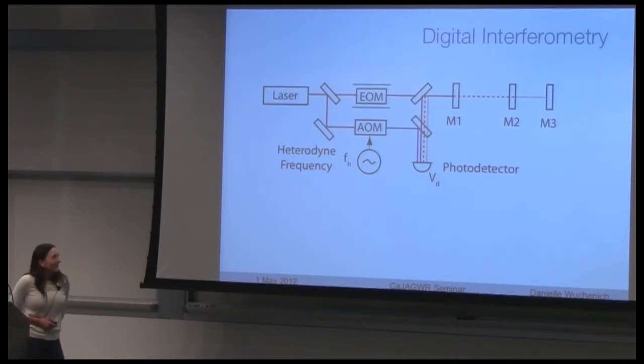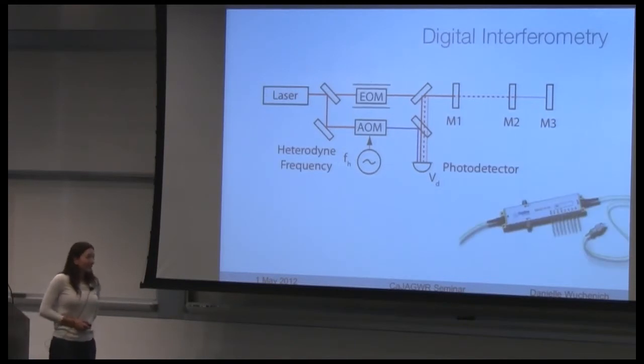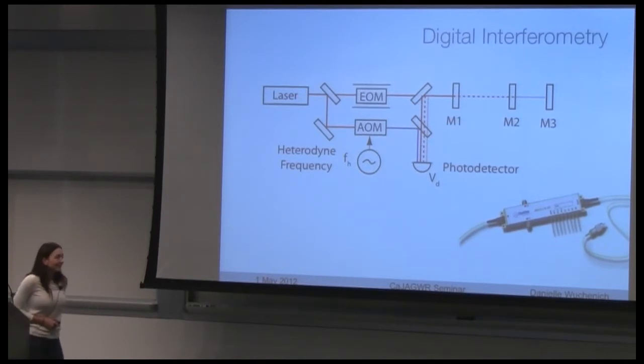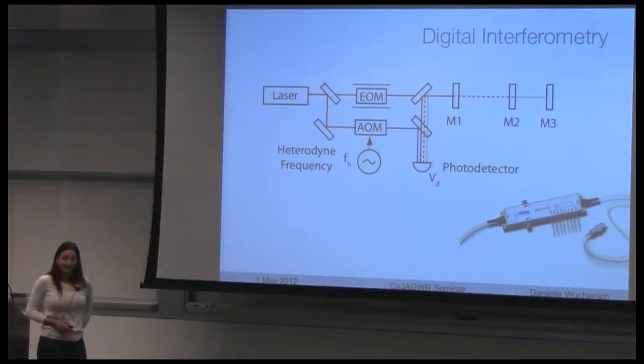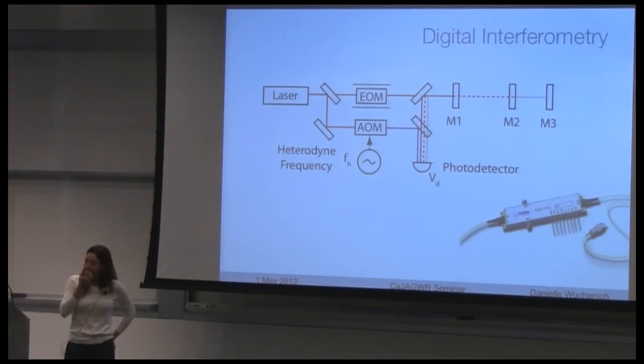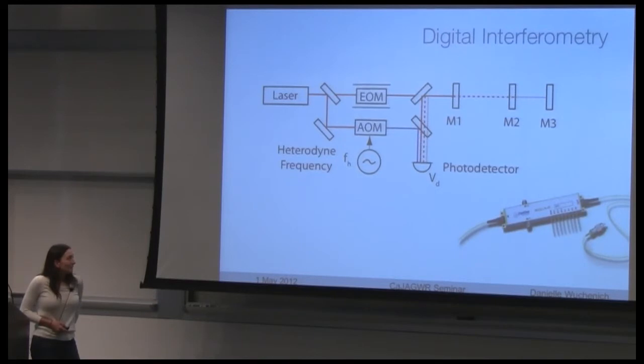All you do is essentially add an electro-optic modulator. And in our experiments, we're using these fancy fiber-coupled integrated optic waveguide modulators, and they have really high gigahertz bandwidth, maybe even 10 plus gigahertz, and pretty low insertion losses, and also really, really low VPIs as well, so maybe less than 10 volts even.